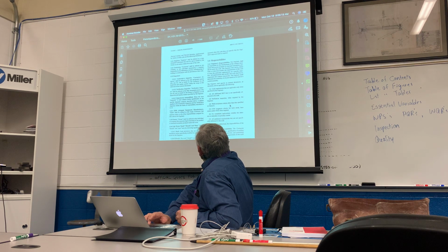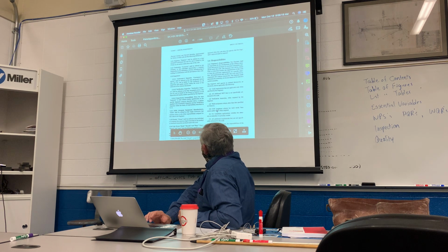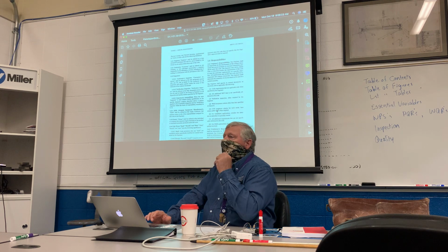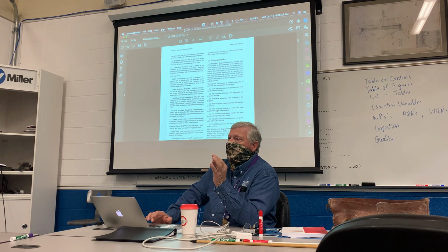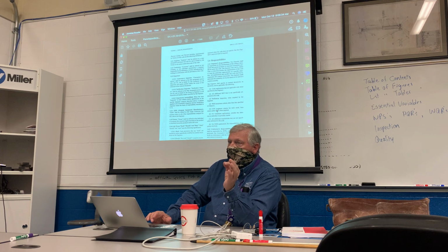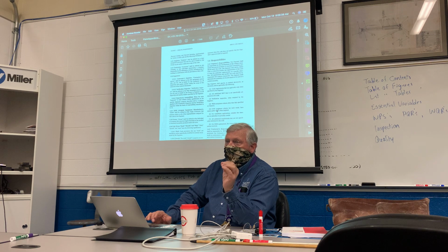Weld acceptance criteria other than specified in clause 6, which is inspection. CVN test. What is CVN testing? No idea. Charpy V-notch. When do we do Charpy V-notch? CVN testing, when the material has to have an impact toughness at a lower temperature.